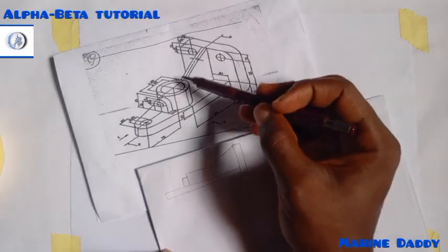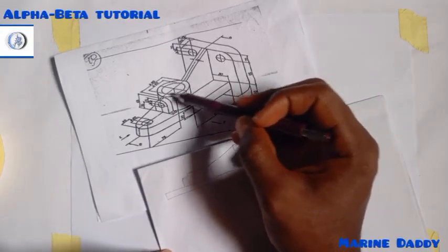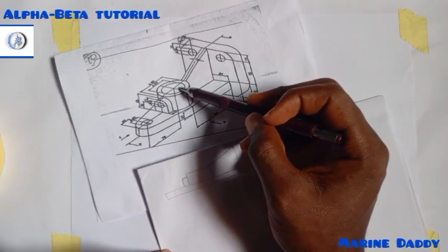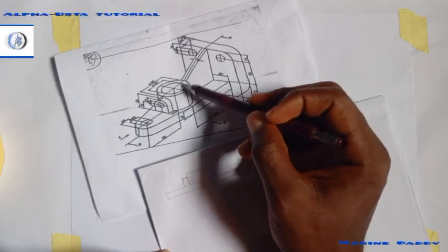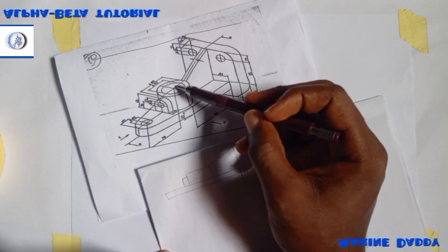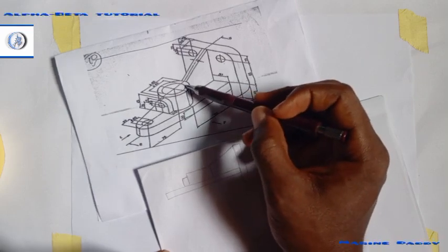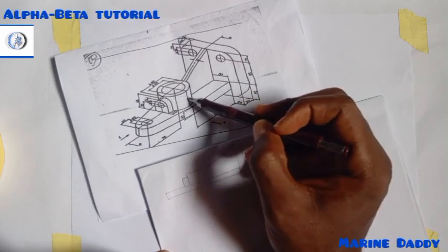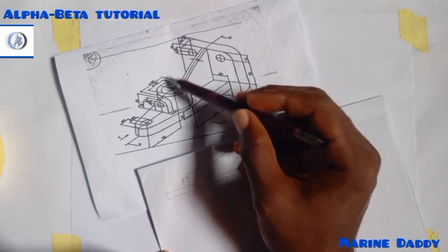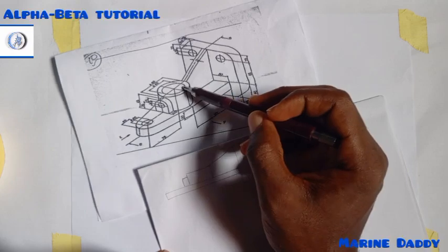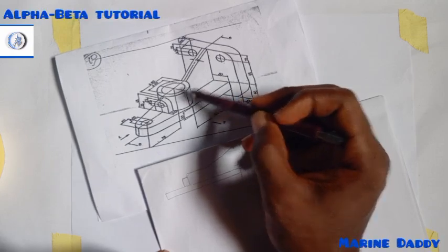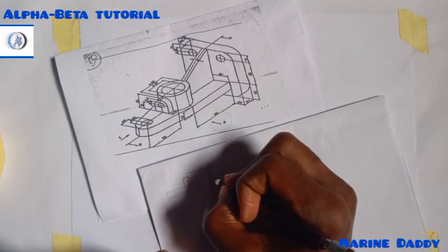So which simply means that from this side I will not see the hidden details, which is the internal part of this side that looks like a cylinder or a well, I don't know. You understand? I won't be able to see it, but I know that there's something there. From this I won't be able to see it, but looking at it from the top, I can easily see this here, which means that I'll use a broken line to identify it. I'll put a broken line here.